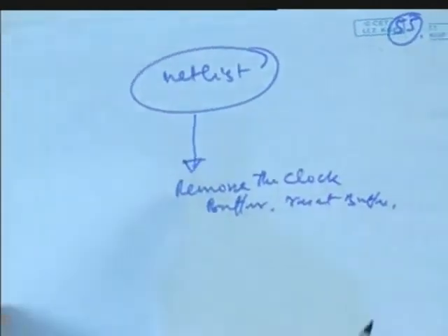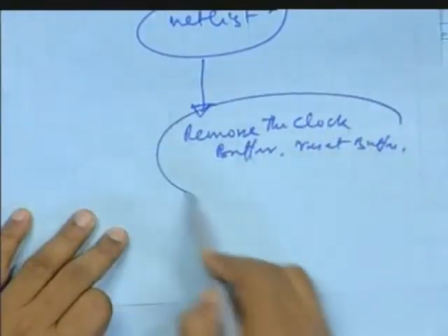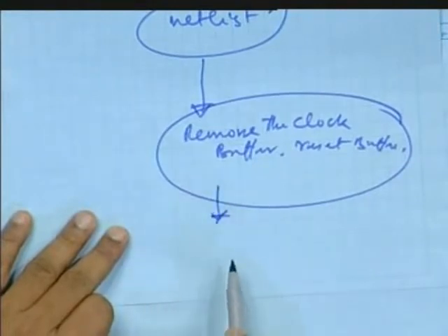Why? Because the synthesis tool did not have the placement knowledge, so it worked in a different way. Now you have the luxury of the exact estimated placement. You'll be doing some rough placement and all. So when you do this, after that you go for a rough placement.